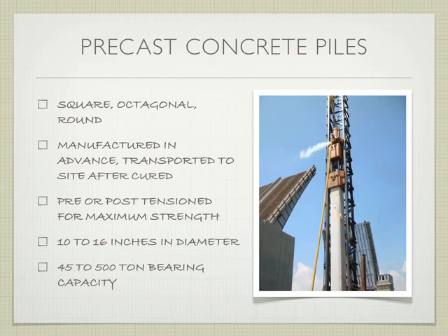So one of these precast places, which we will talk about, I have videos of this process and how they make them, and we'll do that in 3 lectures. But you have to be able to get these, right? You can make them almost as long as you have formwork to make them, but you somehow have to get this to the site where you need it. So there are some limitations for how long they can be. You can't weld them together and make them longer. They have to be cast in one piece, right?